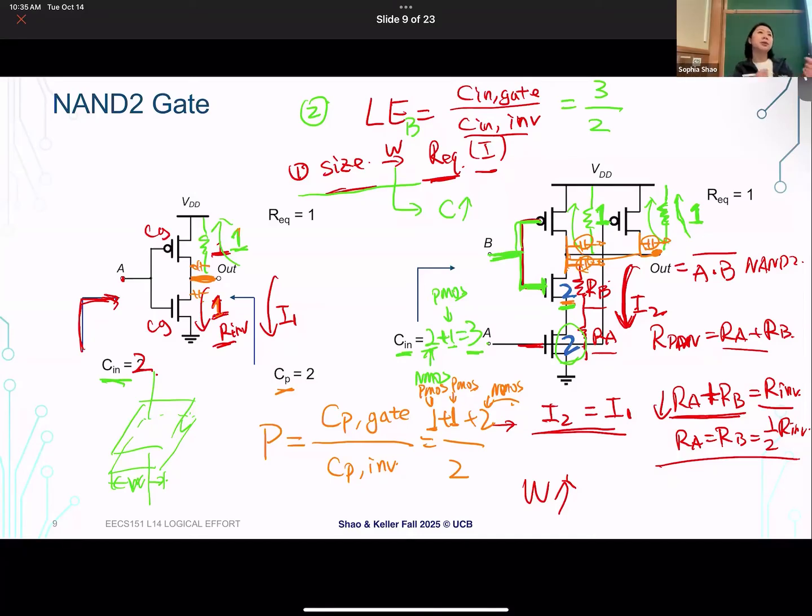It's basically which drain capacitances are connected to the output. If you want to go further, we'll talk a little bit more about how you use Elmore delay to do this kind of fine-grained analysis. Then we'll actually have different paths there. But for this first order approximation, you basically look at the drain node and look at all the drain capacitance that's connected to the output.